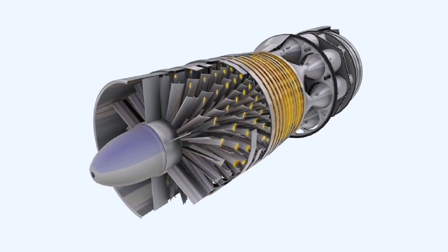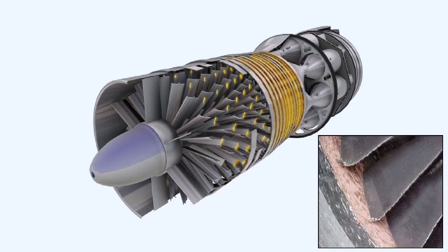Another problem which may occur is that of blade rub, where the rotor blades come into contact with the compressor casing. If blade rub becomes excessive, which might occur through mechanical failure, sufficient heat from friction would then be generated to ignite the titanium. This would, at best, require expensive repairs, or, at worst, cause an airworthiness hazard.